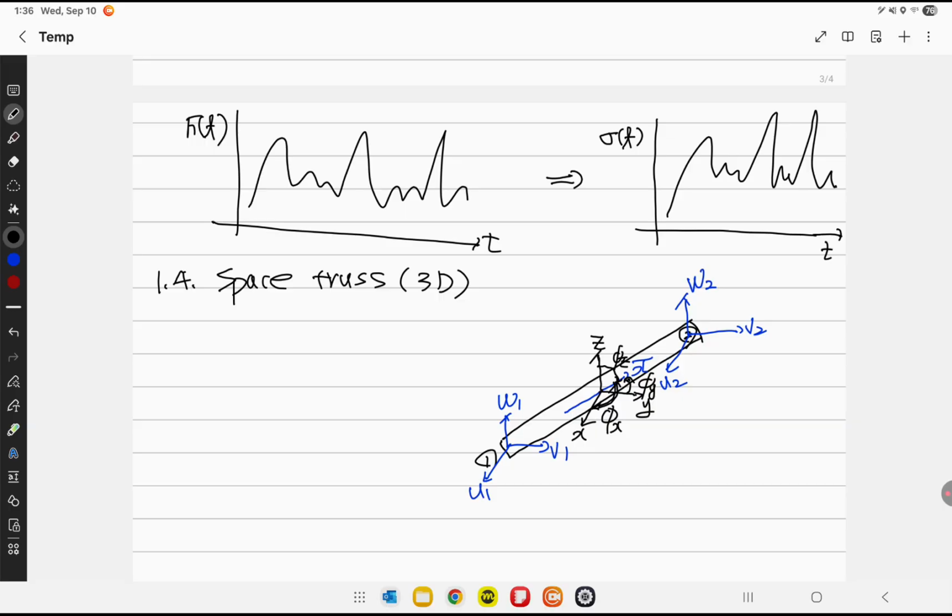Then the direction cosines are L equal to cosine phi x, M equal to cosine phi y, and N equal to cosine phi z. So you have x, y, z, three angles. Why didn't we have that in the previous plane case? Because we only measured the angle from the x-axis, cosine p, but from the y-axis to the x bar was cosine of 90 minus p, which is actually sine p. So instead of cosine 90 minus p, we use sine p. But these are direction cosines.